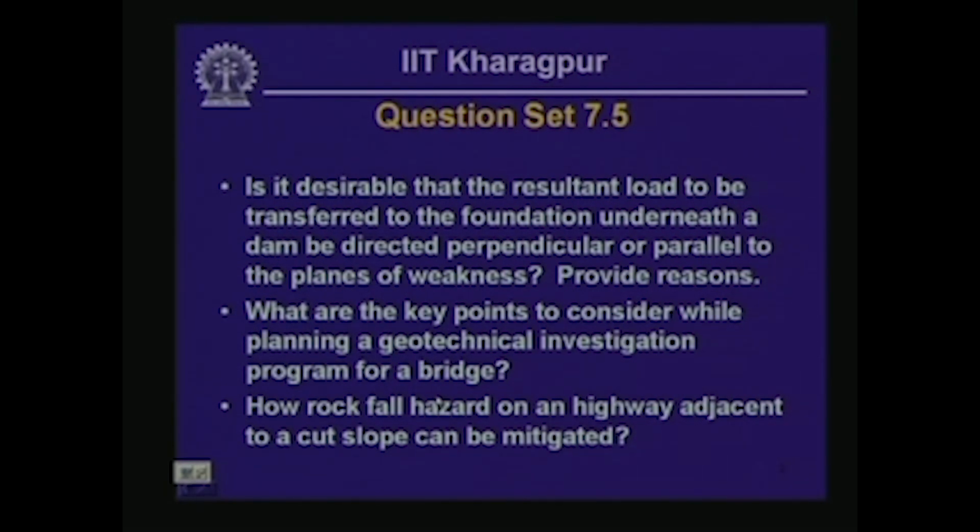So it is preferable that the orientation of the resultant of the load to be transferred is perpendicular to the bedding direction, number one.